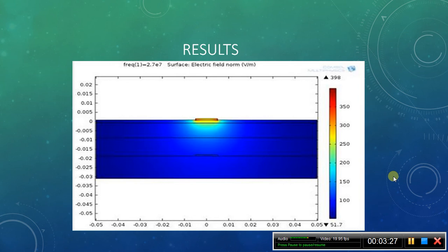An electric field resembling that which the phone would generate was used to obtain a simulation in a form easily relatable to the IEEE C95.1 standard. The results were in the form of electric field strength. A field strength of 100 volts per meter was used for the X and Y components, while the Z component was 0 volts per meter.